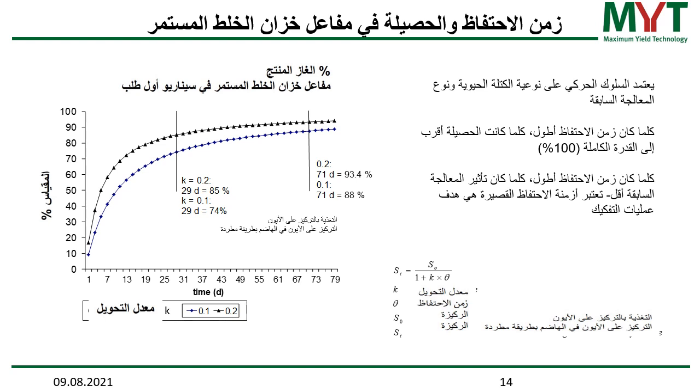If you assume a degradation rate of first order kinetics, then the equation on the right side would look like that. This is the first order kinetic for a CSTR system, and these two curves are actually the depiction of this equation.